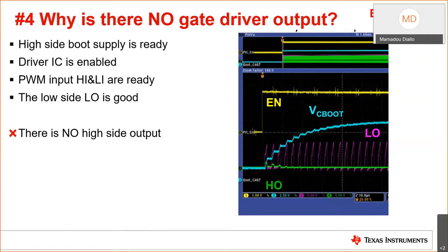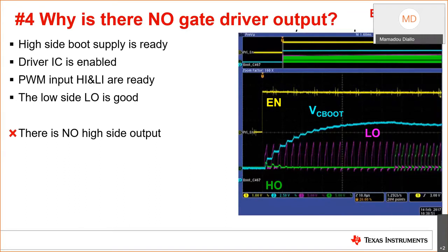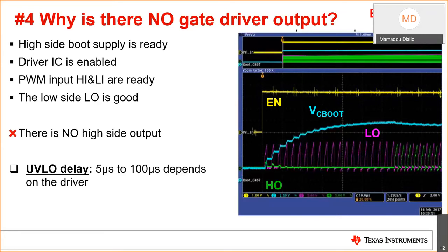This design did not take into account the UVLO delay occurring during power up, leading to skipped pulses or missing pulses. We can see the HO pulses switching 50 microseconds later after the supply has reached the UVLO rising threshold. This UVLO delay is dependent on the driver and must be accounted for in all applications.